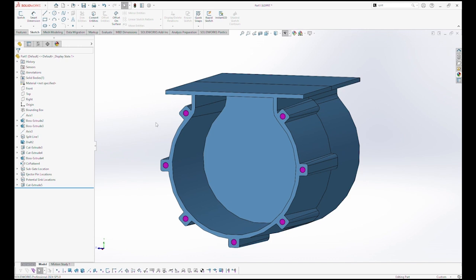Typically in micromolding, we try not to do an ejector pin smaller than 15 thousandths of an inch. It's a good point of reference for designing these small parts because, while we can create them smaller, you certainly can, the repeated force of pushing this part out of the cavity could end up bending those ejector pins, and you'll be replacing them and have high maintenance. 15 thousandths is about as small as we like to go here at Accumold. And so we created those ribs so that we would have some surface area for those 15 thousandths diameter ejector pins to push that part out.